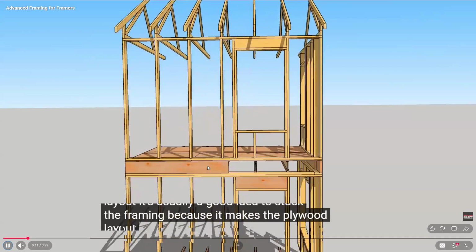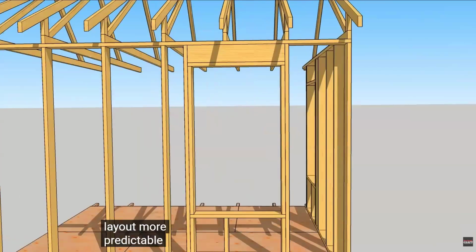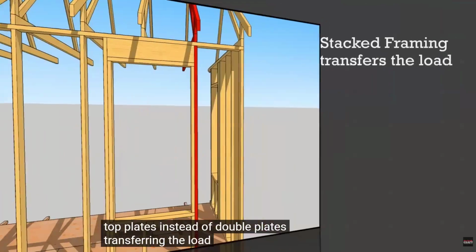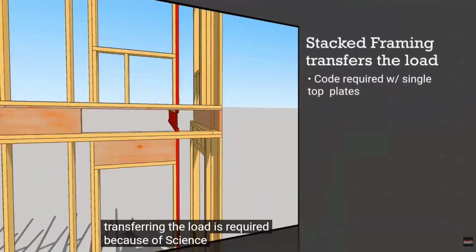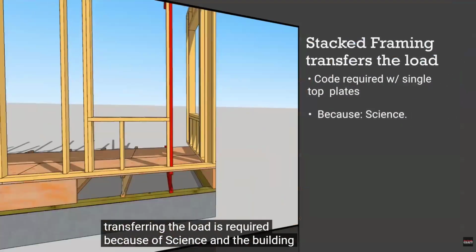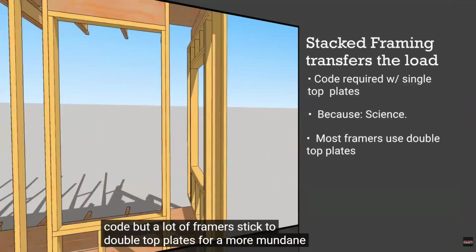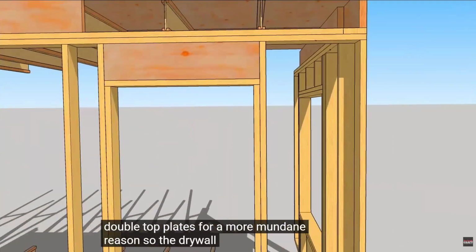Makes the plywood layout more predictable. But if you're using single top plates instead of double plates, transferring the load is required because of science and the building code. But a lot of framers stick to double top plates for a more mundane reason, so the drywall fits.